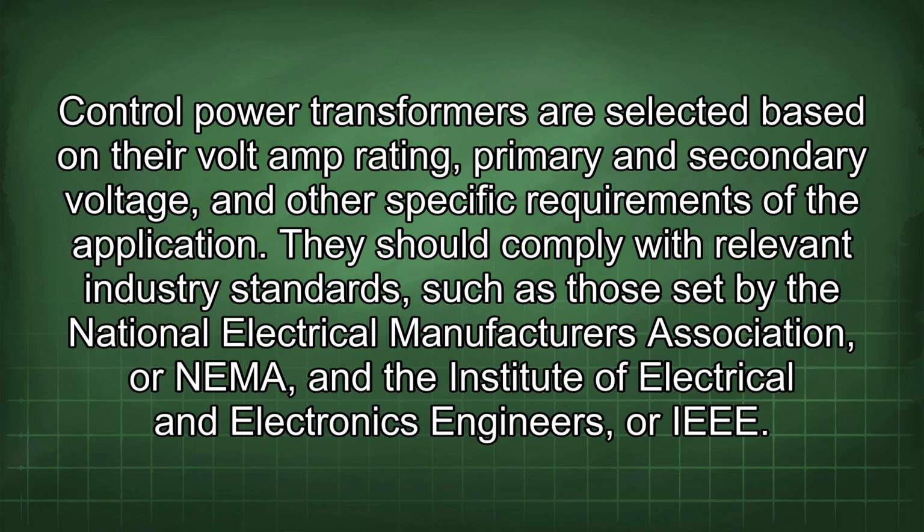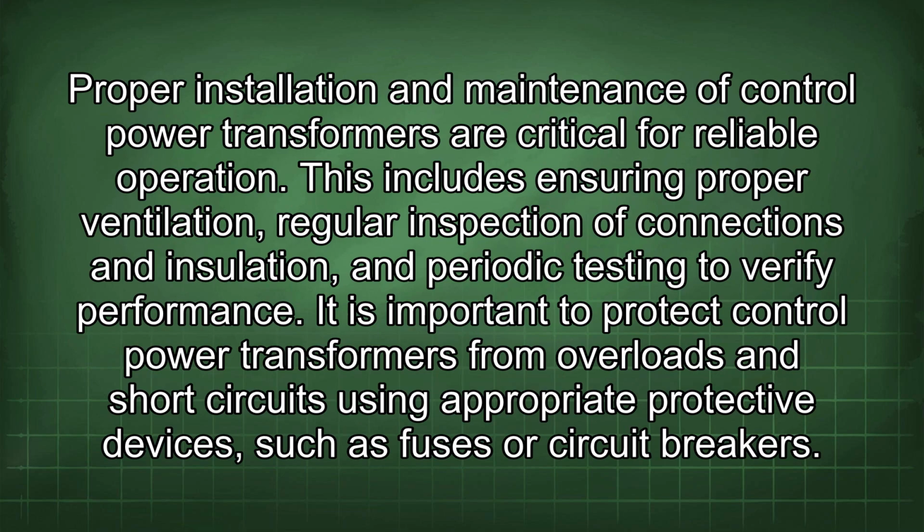They should comply with relevant industry standards, such as those set by the National Electrical Manufacturers Association, or NEMA, and the Institute of Electrical and Electronics Engineers, or IEEE. Proper installation and maintenance of control power transformers are critical for reliable operation. This includes ensuring proper ventilation, regular inspection of connections and insulation, and periodic testing to verify performance. It is important to protect control power transformers from overloads and short circuits using appropriate protective devices, such as fuses or circuit breakers.